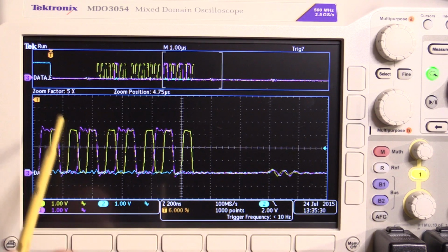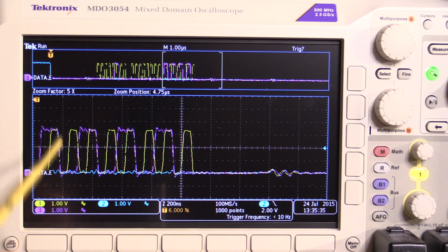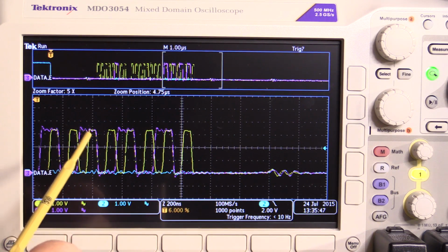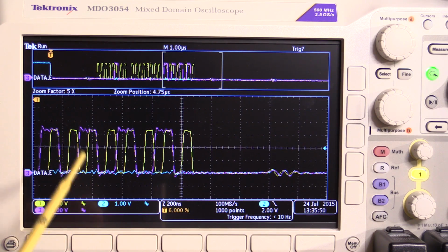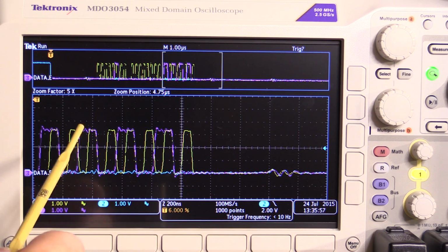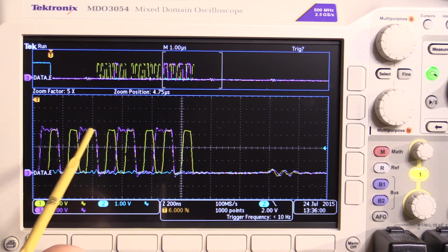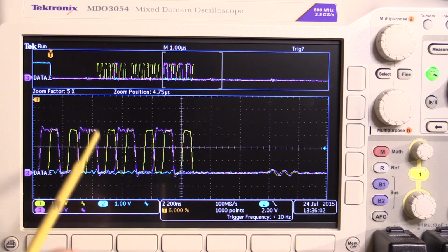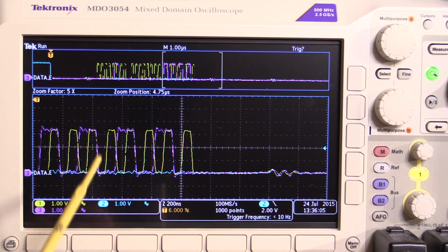And you can see here that the chip wants to clock in the data on the negative edge, but that's coinciding with the data itself falling down too. So like I said before, you've got a 1 and it's clocking down, then you've got a 0 here, but look at this one. The data is now coming up because the master thinks that it's only going to clock on the positive edge. It's quite happy to change the data line on the negative edge to the new value, which is going to be a 1, because it knows it's going to clock it out to the slave device on the negative edge.